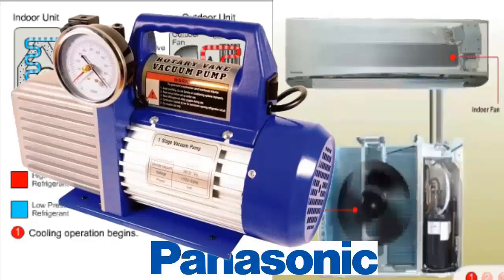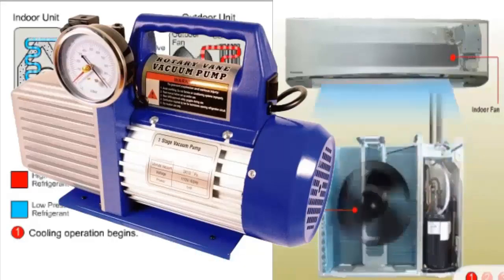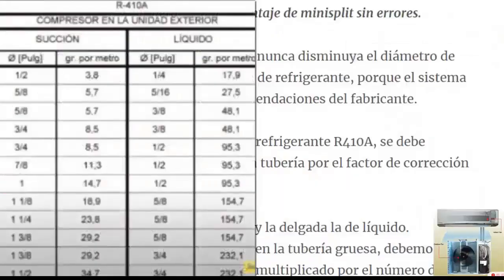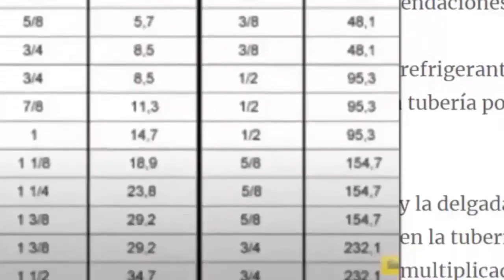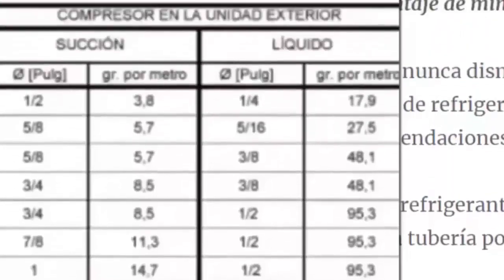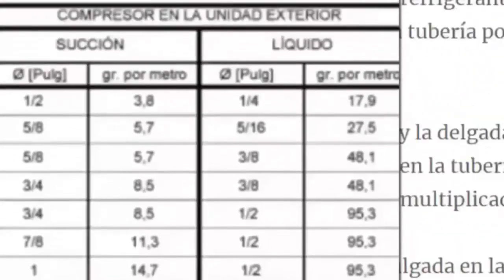B. In addition, the vacuum test can help detect a possible leak before releasing the refrigerant located in the outdoor unit. Error 7. Refrigerant misadjustment, adjusting the final refrigerant amount when there is lengthening or shortening of the pipes.